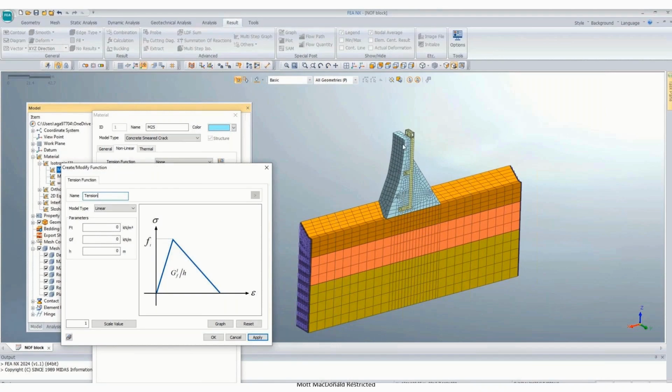Various codes provide that at a particular level, uplift can be reduced to half, and then some permeability of the concrete we can assume, we consider it half, and then consider it to 0, something like this. Those were for the manual computation of stresses.